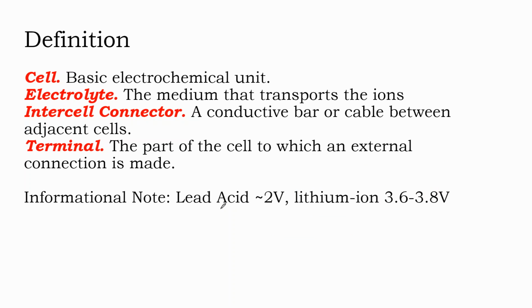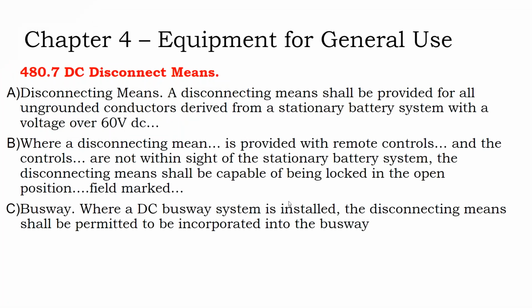And so the pragmatic difference between charging a 48 volt lithium ion battery bank and charging a 48 volt unsealed lead acid battery bank is that with the lithium ion charger setting, once you hit that maximum 48 volts, it immediately is going to throttle back the charge, whereas lead acid you could sustain at a higher voltage, which has some maintenance benefits that are simply not available to sealed batteries.